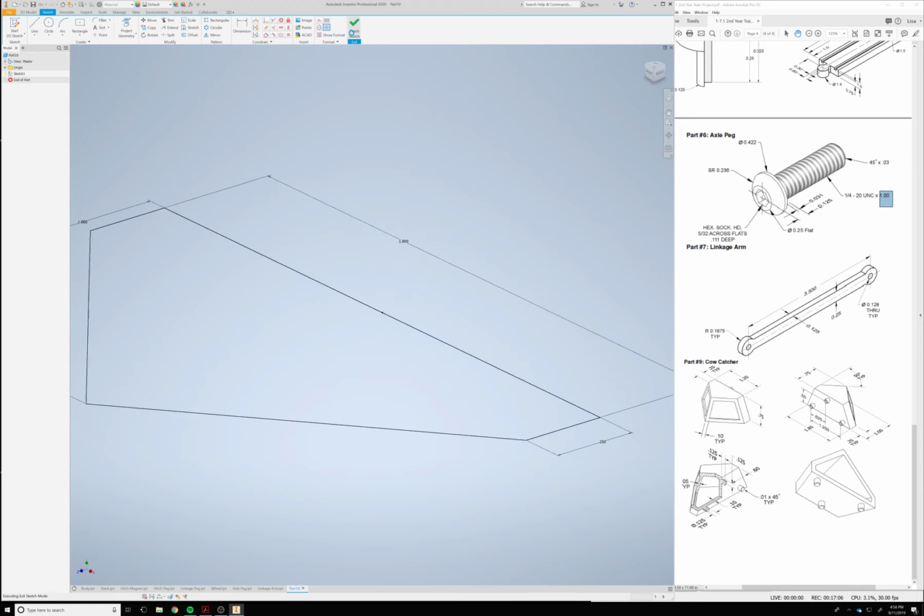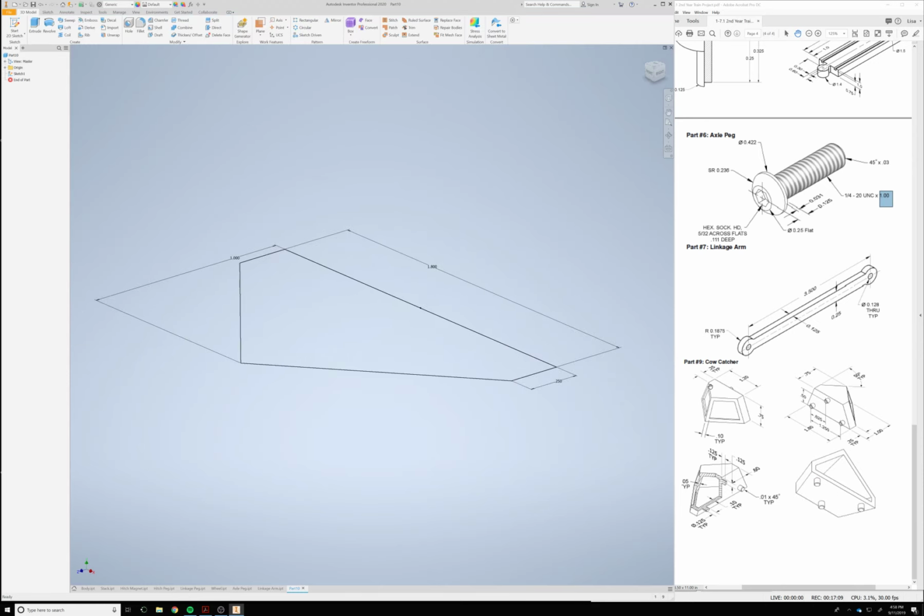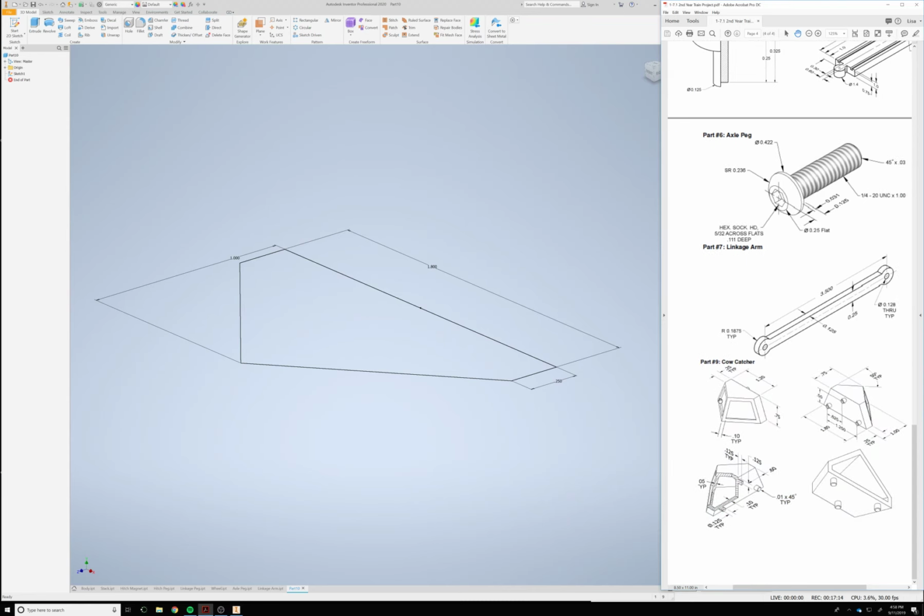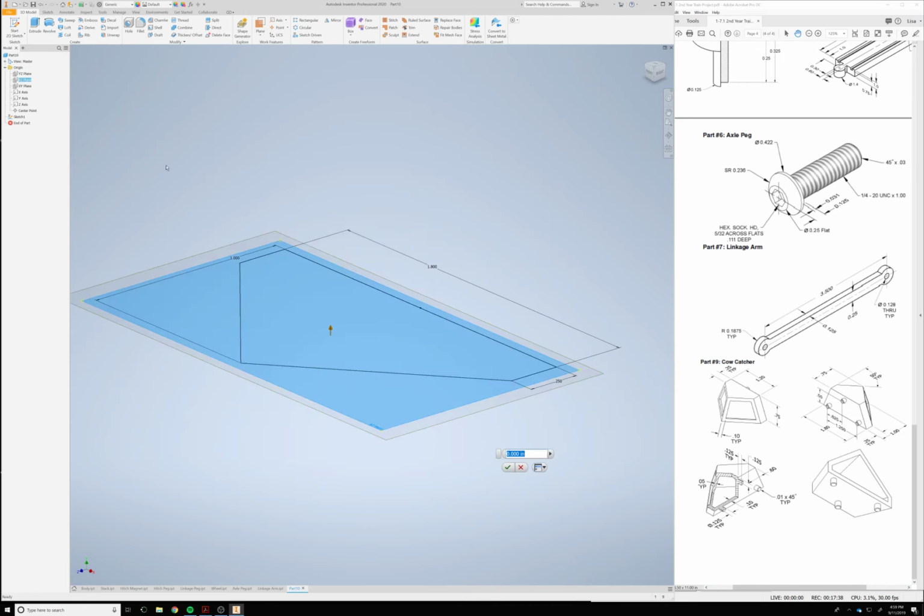Finish your sketch. What we are going to do is, because the top profile up here has a different size than the bottom, even though they're the same shapes, they're different sizes. So we need to go ahead and create an offset plane, because if we extrude it, it's just going to be a solid, straight, even thing. What we're going to be using is loft. So we're going to create an offset from plane. We're going to offset from the XZ plane, and we're going to offset it by 0.75.